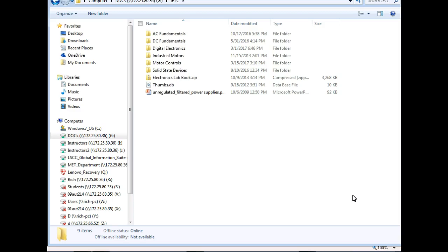So that specification matters, because when FANUC makes a robot, they have no idea what type of tool you're going to mount on that thing. Robot manufacturers are not usually in the tooling business. They make robots, but they put a plate out there that the end user can mount tools on. So when you put a tool on there, that's going to subtract from your payload. Right? You understand? Yes or no? What you're trying to pick up.